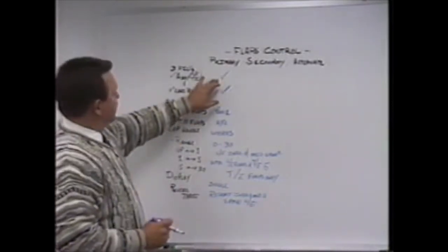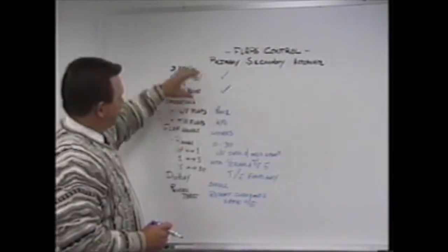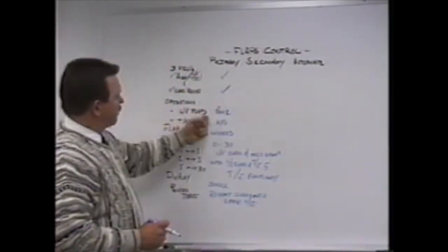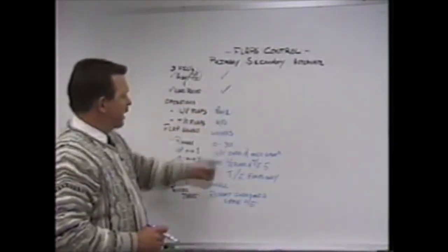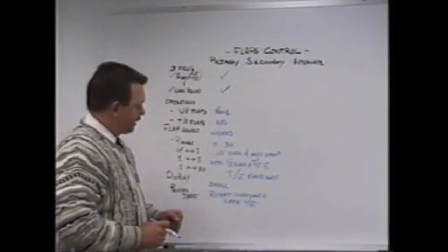So symmetry protection, both leading and trailing edge flaps, load relief on the trailers only, and that's a function of the 3 flap control units to provide those 2 protective features. Leading edge flaps are pneumatically operated, trailing edge flaps are hydraulically operated. The flap panel does work. You can select anything from 0 to 30.